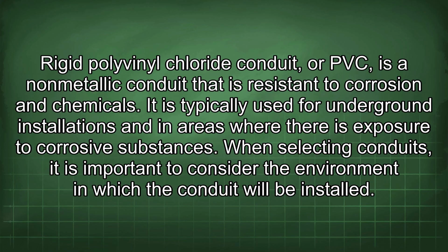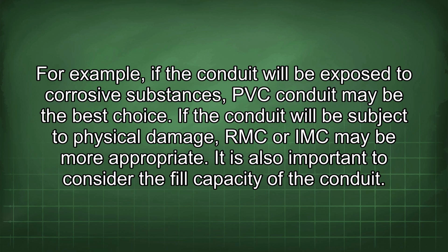When selecting conduits, it is important to consider the environment in which the conduit will be installed. For example, if the conduit will be exposed to corrosive substances, PVC conduit may be the best choice. If the conduit will be subject to physical damage, RMC or IMC may be more appropriate.